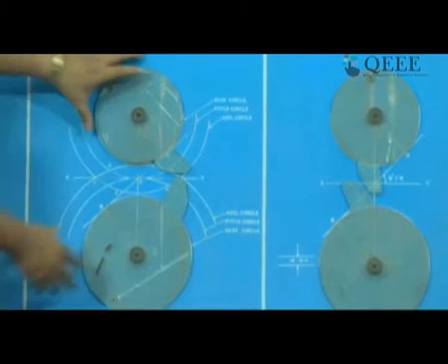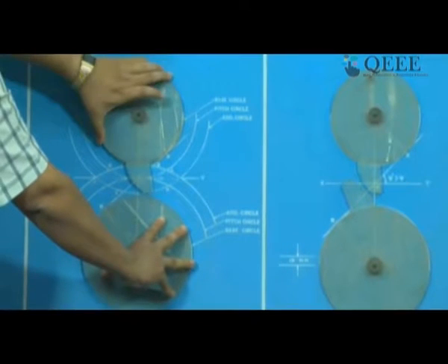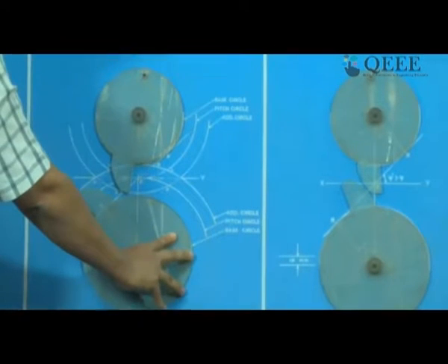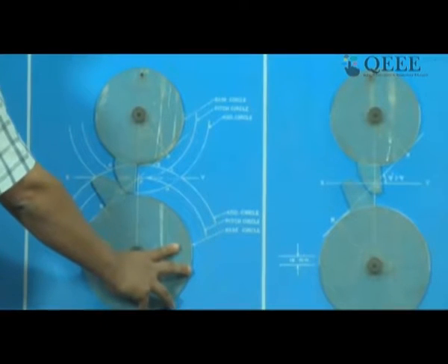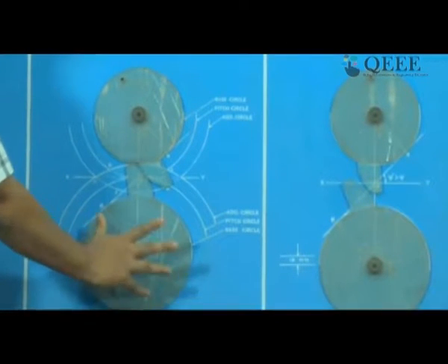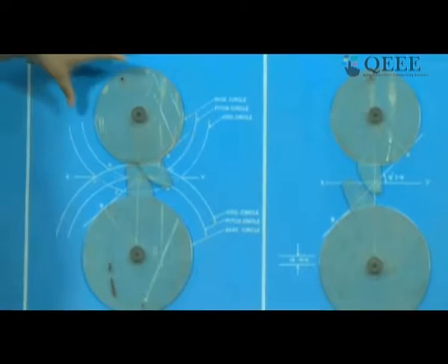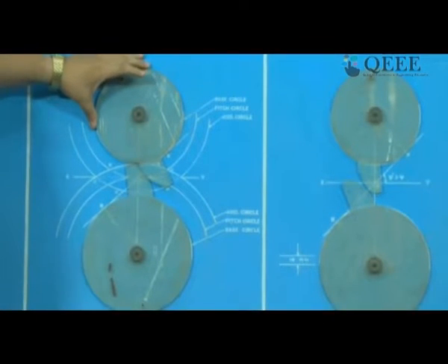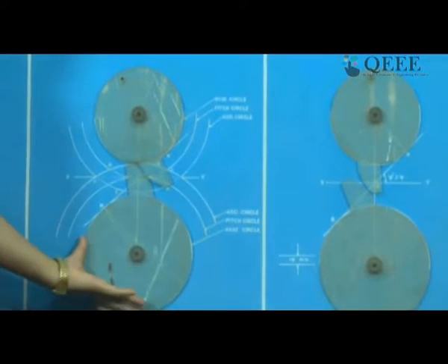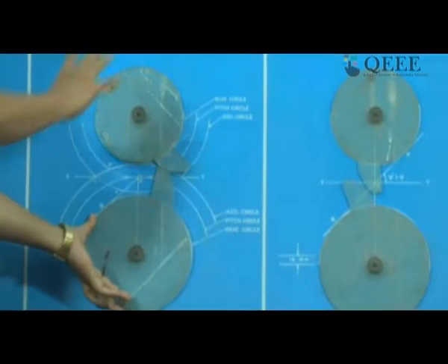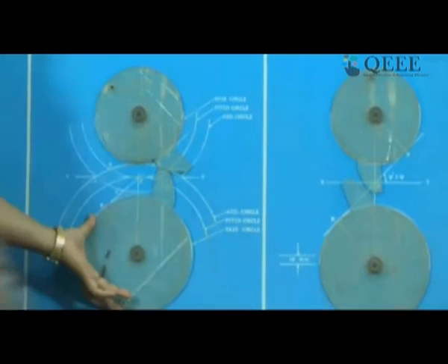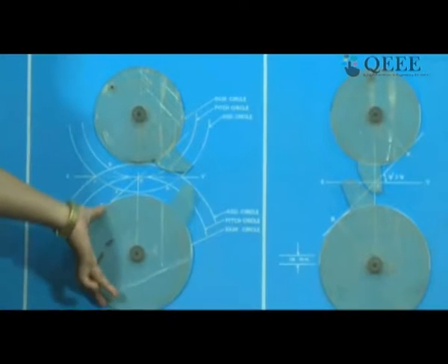So the first point of contact happens when the addendum of the driven gear has contact with some portion of the driver gear. The point of disengagement happens when the addendum of the driver gear is passing through a certain point of contact of the driven gear. So this is the last point of contact.